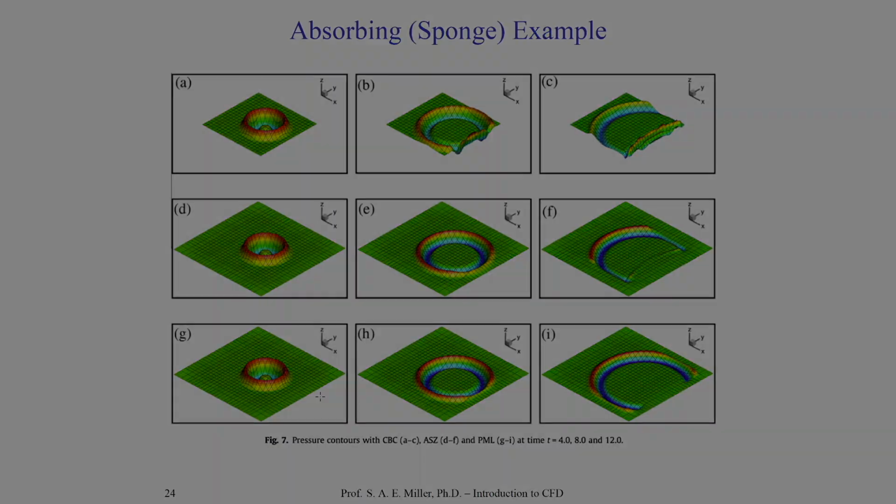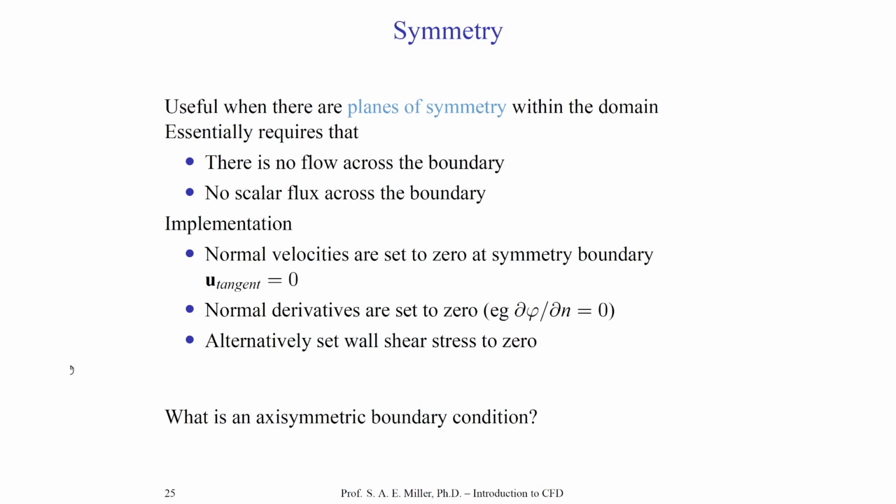which are the same. Another important boundary condition which you should absolutely be aware of and take advantage of, especially in steady simulations, is the so-called symmetry condition. The symmetry condition is actually equivalent to the no-slip condition. They are exactly the same, but they're just implemented a little bit differently in the codes.